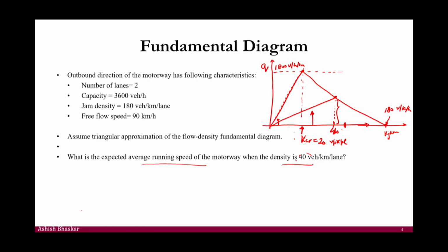One of the common mistakes that we make in the calculation here is we mess up the units. If you have used 180 here, vehicles per kilometer per lane, and simply use 3600, all the calculations will be wrong. So never, ever miss the units in any engineering calculations. 36 has no value for me. 36 plus what? Is it vehicles per kilometer or whatever the unit behind is? I think in the very first lecture of engineering, when you are taught engineering statics, they talk about the significance of the units. And they said this is the foundation.